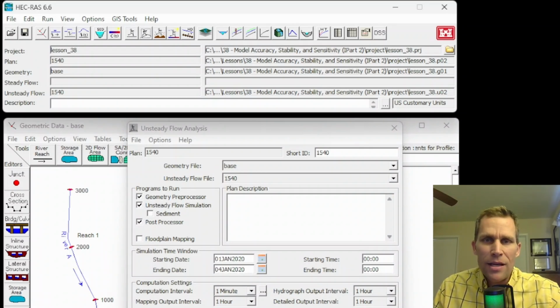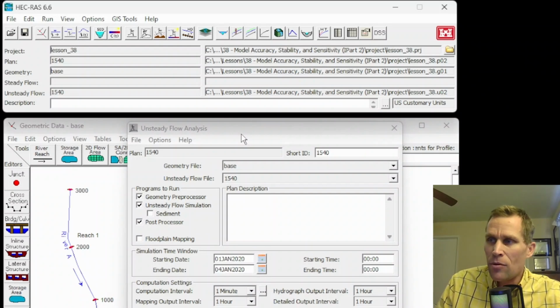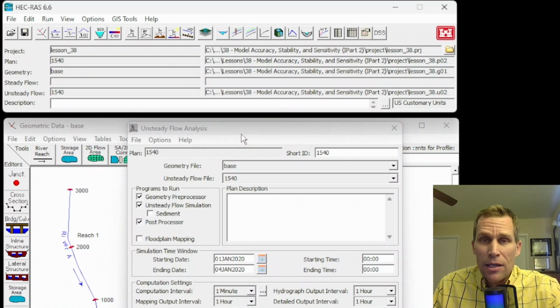Okay, we're going kind of long in this lesson, so let's just do one more. This is number 8 now, cross-section geometry and table properties. The problem here would lie if the hydraulic properties tables have an abrupt change to their value, such as the flow rate or the conveyance, or storage with a small change in elevation.